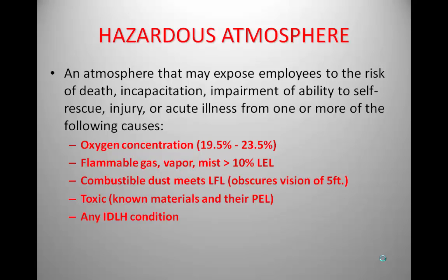At 2 to 3% oxygen concentration, that person is going to go unresponsive in a matter of seconds and it is likely a fatal exposure. Around 12 to 14%, it's not necessarily a lethal level, but what it does to the body is pretty bad. It increases respirations, it causes fatigue, and it also causes poor judgment. So these simple processes of how to open or close a valve, those processes are altered at that level. Anything over 23.5% oxygen enriched is bad for flammability purposes.